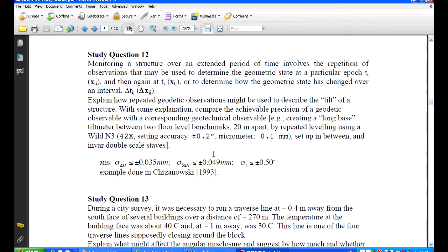So now it's a question of looking at the instrument and coming up with how well we can figure out this delta delta H. Because again, it's similar to the extensometer business. If you do the full propagation, you see that the uncertainty in the distance doesn't have much influence because it's in the denominator and squared as a coefficient. So our main concern is the uncertainty in the delta delta H, the height difference divided by the S.